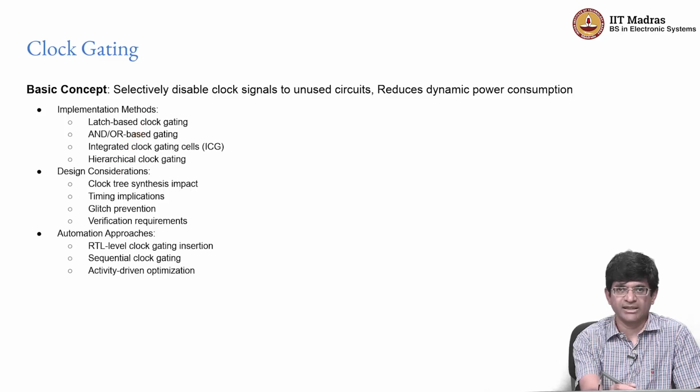So the flip-flop by itself does not see a transition, and therefore the flip-flop remains in frozen mode, and there are no transitions at the output of the flip-flop. So there are various kinds of hierarchical clock gating techniques, where you can basically turn off the clock to an entire subsystem, or having clock gating cells that are integrated within parts of a design. All of these are circuit level techniques that are commonly adopted in practice. Now all of these in turn have impacts on various aspects of the design process.